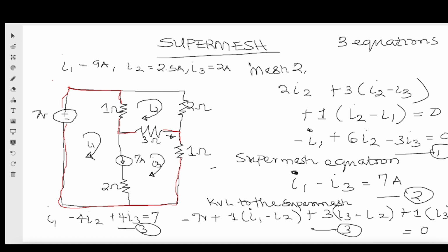So what about the situation where a dependent voltage source is controlled by a current, or the converse, where a dependent current source is controlled by a voltage? Provided that the controlling quantity can be easily related to mesh currents, we might expect mesh analysis to be the more straightforward option. But likewise, if the controlling quantity can be easily related to nodal voltages, nodal analysis may be preferable.